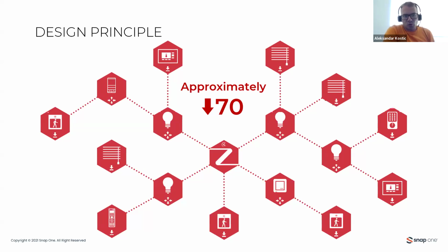The most practical way to achieve this is to just place one CA1 close to the lighting controllers, and the main purpose of that CA1 would be just to provide Zigbee coverage for the light control, and to provide secure and reliable Zigbee communication with lighting control.